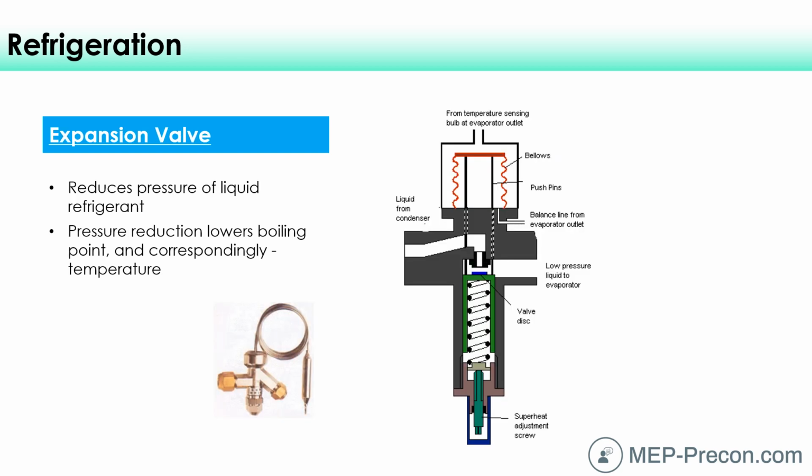All right, let's talk about the expansion valve. And again, it could be just an orifice, but we use a valve because that's a little bit easier for us to be able to control certain aspects of the refrigeration cycle, like how much it's loaded up, different capacities, different sizes of the refrigeration cycle. So we can control the orifice size with a valve here.